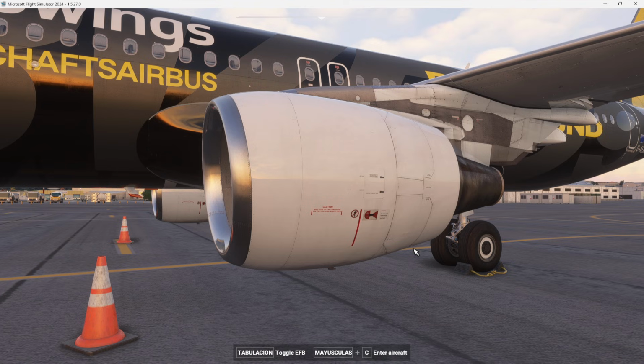It means that this 80% is not going to pass by either the low pressure or high pressure compressor, or the high pressure or low pressure turbine. It is going to bypass the engine, and this is used for most of the thrust. Okay? We use it for the thrust.